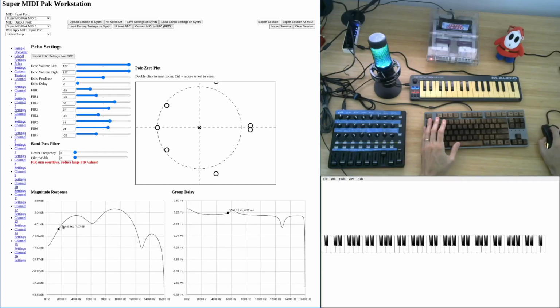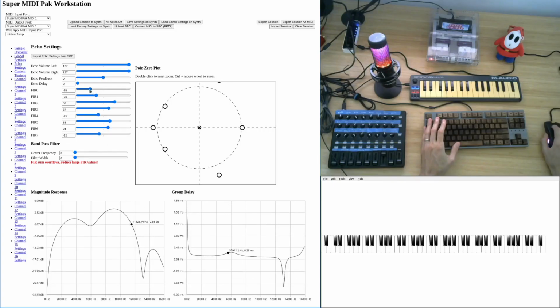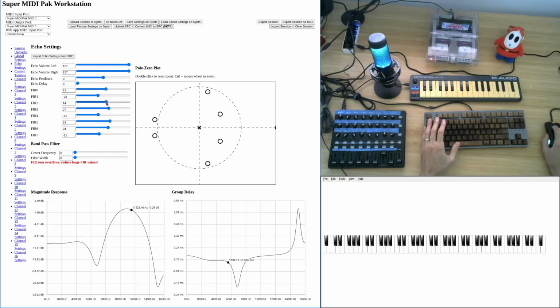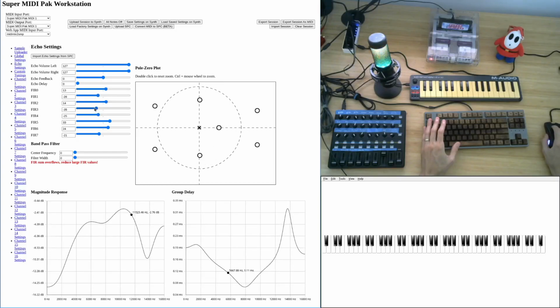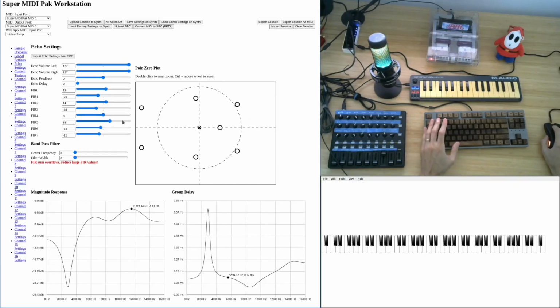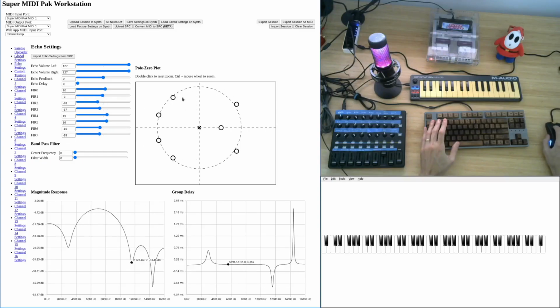And you can see the effect on the magnitude response in real time. But like I said, it's not really clear how we get a magnitude response. There's no real systematic way of getting a magnitude response we want just by manipulating the FIR values. It's much easier to move around the zeros of the filter to get a response that we want.